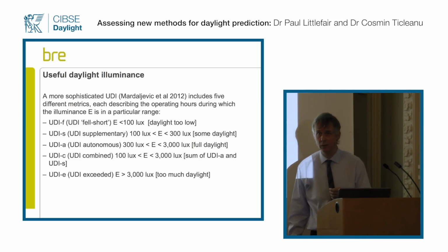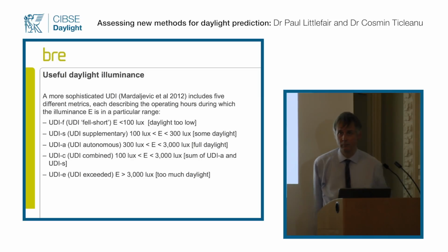Sorry, Joe, did you have a... Well, I was going to make precisely the point which you've just made, that glare doesn't depend on the illuminance on the horizontal plane. When we're dealing with artificial light and the glare index, we don't attempt to relate that to horizontal illuminance, and it's quite stupid to do it for daylight.